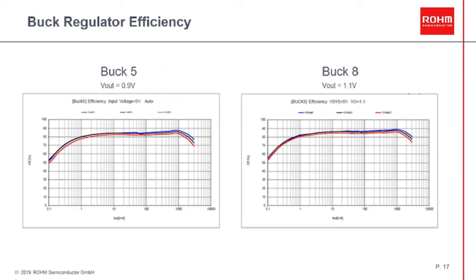The next slide is pretty much the same information for the other two low output voltage bucks in suspend, idle, and run mode. You can see even here that the efficiency performance is perfectly optimized for best thermals and long operational times if your application is battery driven.